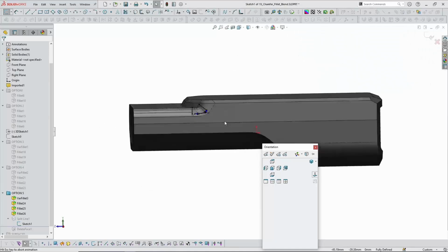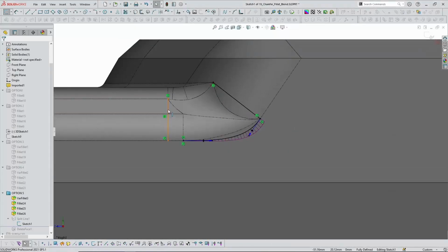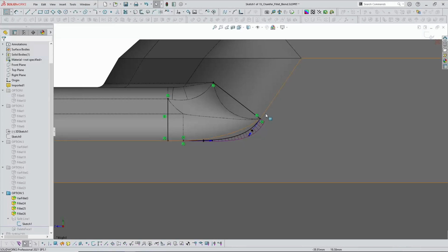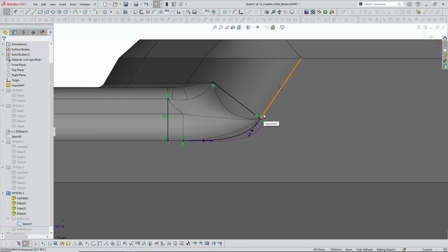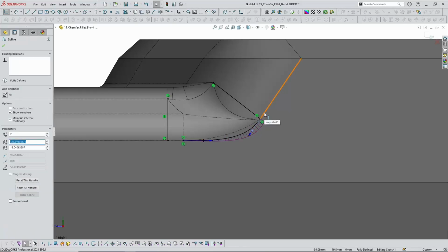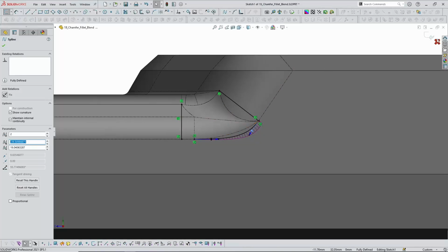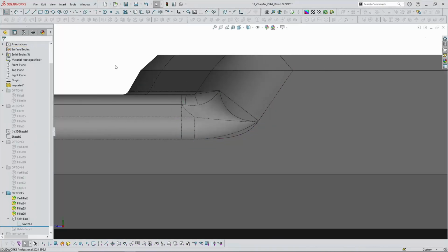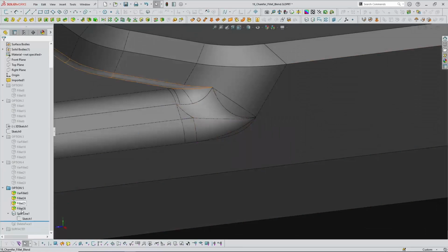And if we examine this sketch, I'm just framing out that portion for the blend, and I have this new spline transition here, but I am beholden to my existing model edges. Like I have to make this spline tangent to this model edge. I can't just start it up here or have it bridge around here. So the inputs of what I'm starting with define what I can and can't do with this delete face patch.